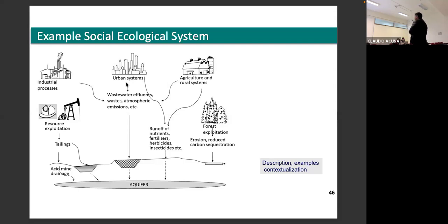Okay? And the good thing, you will have more details. I cannot deliver it, it's also a patented technology. I will not show the reactor, but you will know the reactor because you are my close ones. And this reactor, I will tell you, is a loop reactor. Two columns connected, I inject air in one, generate gas holdup, change the density, and start moving along. This is the reactor for hot bubbles, but the same reactor is the invention for leaching bad particles. Got it? Think about it.